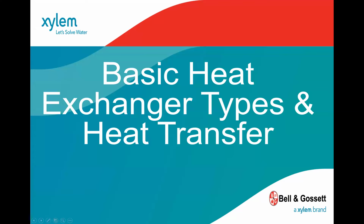So something that sounds a bit more complicated than it really is is the log mean temperature difference. Ultimately, if you have two fluids, the further away those two fluids are from one another, the easier it is to transfer heat, right? So it always wants to go from hot to cold. As you start getting closer in temperature, it's harder to make that transfer, holding everything else constant, surface area, exposure. So this right here just goes a little bit into the importance of having a reasonable log mean temperature difference, which you'll get into a bit more in another slide.